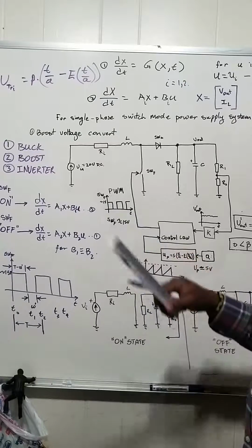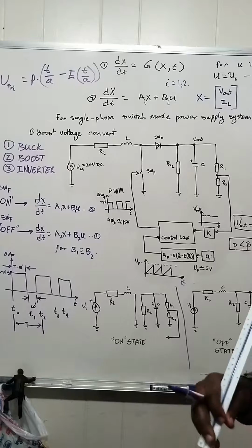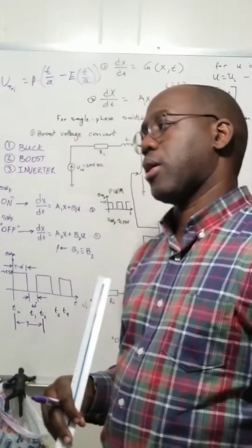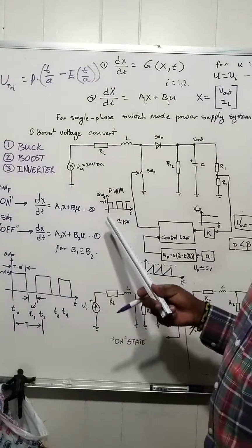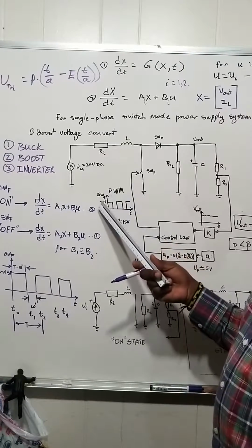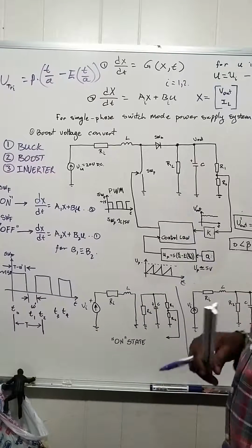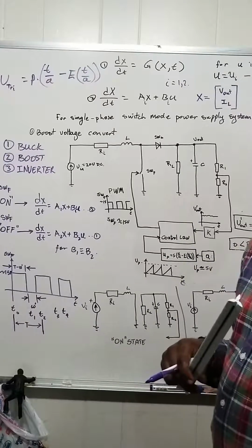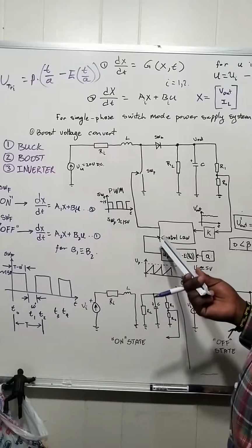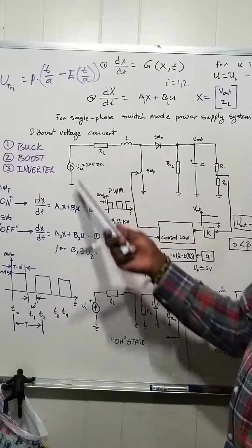The voltage here is approximately 15 volts because these transistors open at anything over 5.5 volts. Anything under that, it may not open. So here we assume that the switching here is at least 15 volts. We definitely know that. And that's coming from our what? Operational amplifier, right? Which is the comparator. And that actually switches our transistor and regulates the circuit.